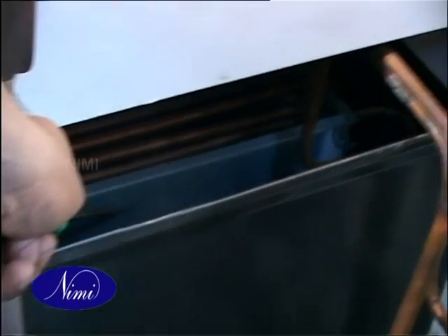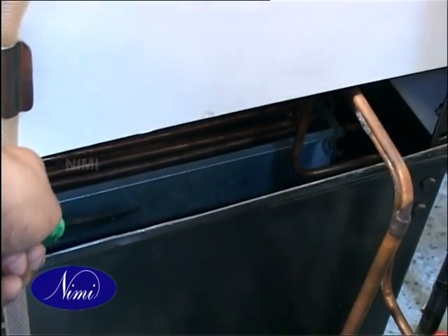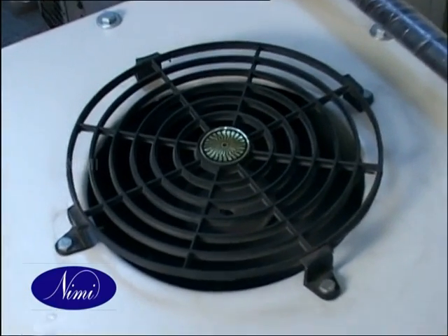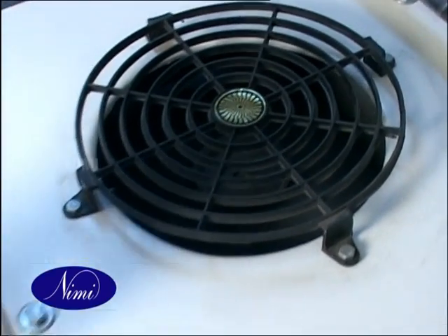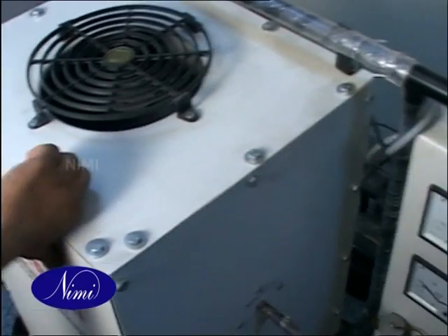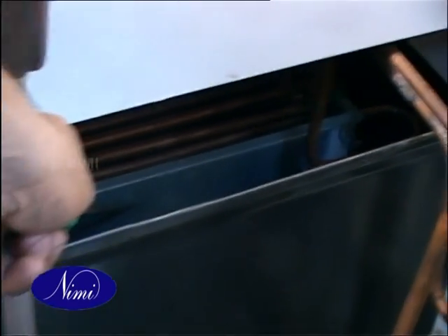Evaporative condenser uses both air and water as a condensing medium with water sprinkled over the condenser coil. A fan installed on the top sucks the air from the bottom side. Air-water mixture absorbs the heat that results in liquefaction of the refrigerant. Water circulating pump regulates the water cycle.